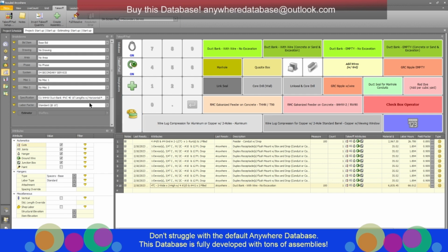So I just encourage you to play around with these and really keep the specs rather simple, like what I did there. Just keep it aligned with what you're doing. Feeder spec with feeders, branch spec with branch conduit, or in the case of the devices, put the branch spec up in the upper part, the device spec down in the lower part. And duct banks have their own spec, and it pretty much just works like that.